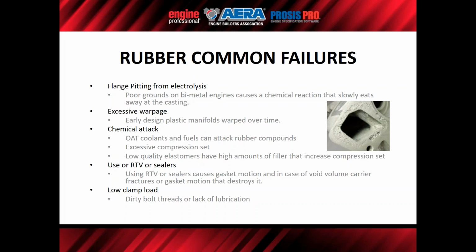That particular E85 fuel will attack some of these rubber compounds that were never designed to accommodate it. So if your car is not E85, don't put E85 in it. You might think you're getting better fuel mileage or cheaper gas, whatever you're thinking, but you're also exposing your car to some issues that are unnecessary from the sealing standpoint. So don't do that.